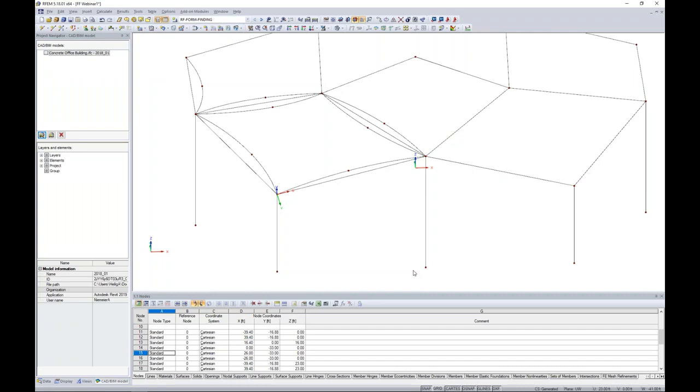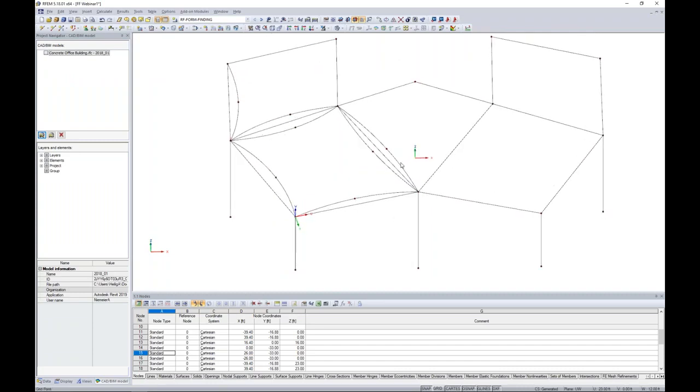Deactivating this grid down here at the bottom, I have these cable elements shown here, and I'd like to show them on the other side. Rather than going through that entire process again with our user-defined grid, we can hold down our control key to select what will be these cable element lines and take advantage of our mirroring tool.